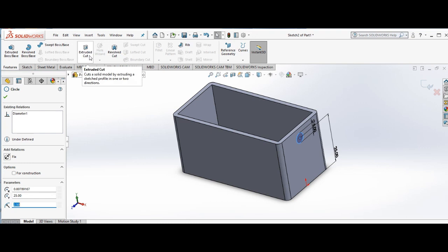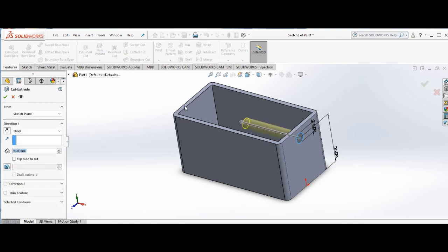So when I click extruded cuts, you can see it moves the cut to a particular diameter, and the diameter here is 30. It's 30. Now let us expand it. So we click on this option under direction. I click it here. You can now select through all, which means it will go through the entire shape. I click through all. Now it has gone from here to here.